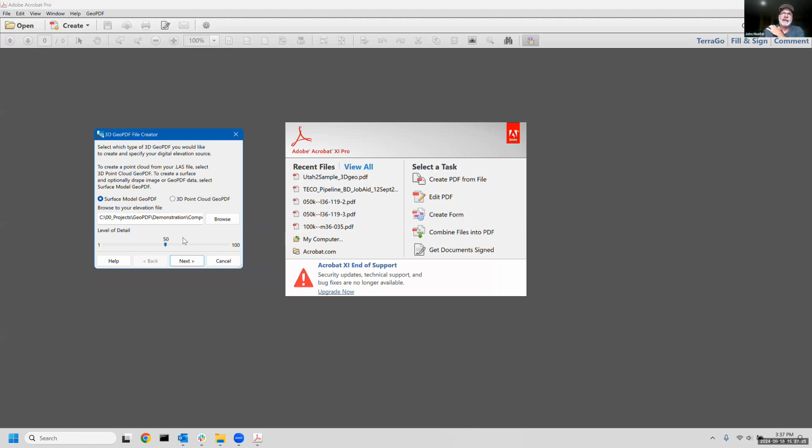I would recommend we try to stay around a gig for the elevation, and we also try to stay within like a 1 kilometer squared area, just for the performance of the tools and generating a model, so it doesn't become too lengthy, or the output doesn't become too large really to share with users.